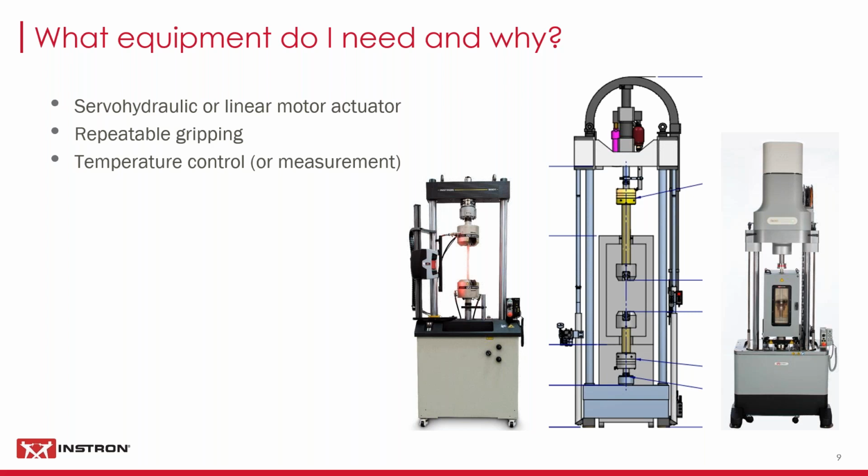And temperature control, as I've just been saying, we need to at the very least measure the temperature. You really do need to monitor it during the test for composites fatigue. But you might want to control it to do tests at, let's say, -30, room temperature and +70, for example.